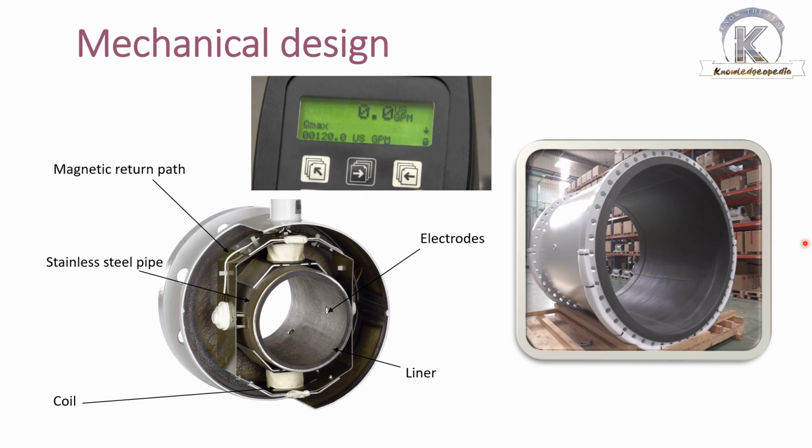This is primarily due to the fact that the induced voltage on the magmeter measuring electrodes picks up the velocity information from the fluid particles throughout the full cross section of the meter. That means it can handle a very wide variety of flow profiles. So unlike a differential pressure flow device, through which you can also measure flow, it's a separate technology.